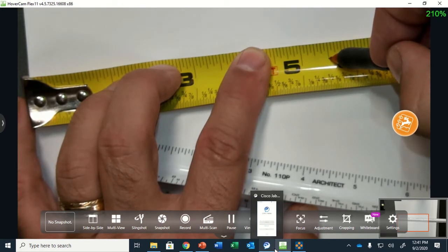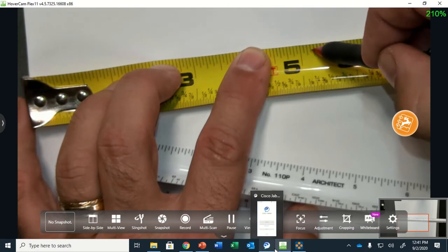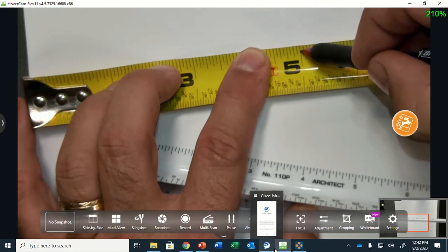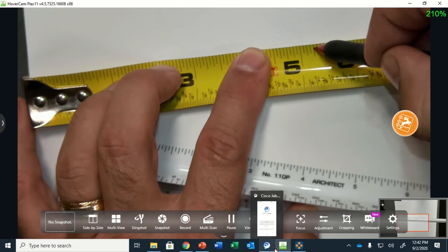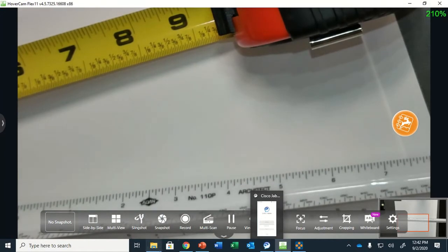We're scaling it down, okay? So 1/4 inch is right here. And 1/8, 2/8 equals 1/4, or 1, 2, 3, 4, 16ths equals 1/4, using fractions. So 1/4 equals a foot. So basically the real life distance of 1/4 inch is now going to represent 1 foot. Okay? So hopefully that helps with what we're doing here.